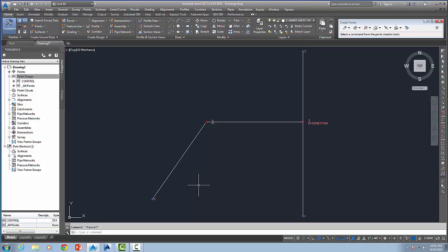Now one is actually delta, and if you think about it, that's what this tangent line and this tangent line represent. These are your delta angles between those two. The other parameter you see is the degree curve, and we're assuming it's highway, so that would be a 30-degree curve. 30 degrees means you don't have a really high velocity on this thing, so it's going to give you a smaller radius, so you're not traveling at 60 miles per hour around this curve.